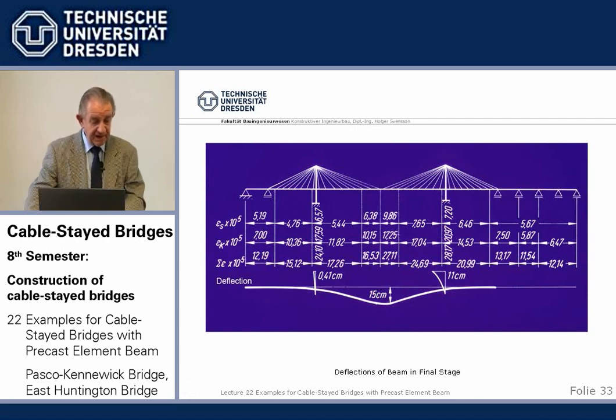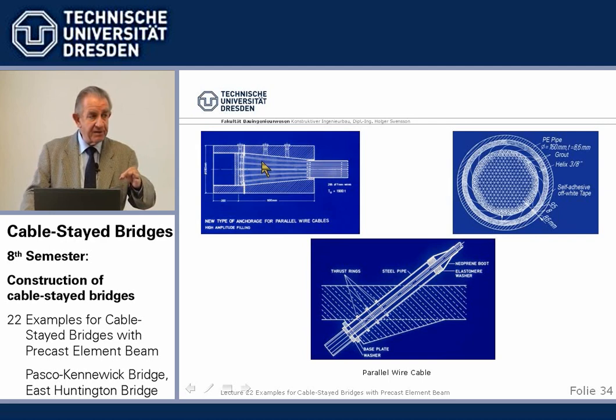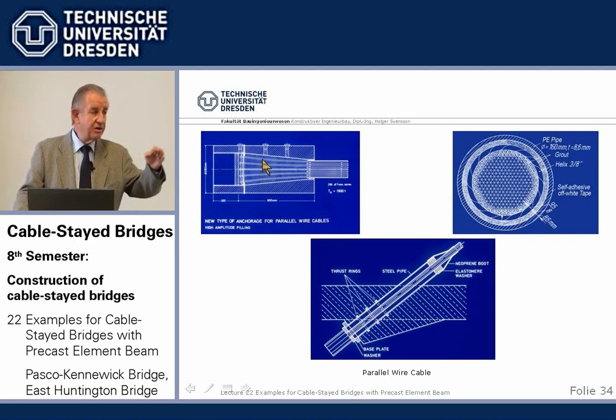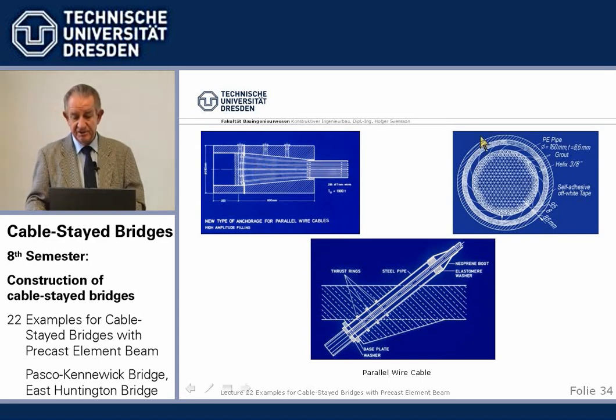Now, stay cables. We used high-M stay cables. I told you all about it. Basically, it's a steel anchor head. The wires protrude and they are fixed with steel balls and epoxy. Cold casting, higher fatigue strength than the hot casting used for the lock coil ropes, where we have the zinc alloy at 420 degrees, which changes the steel, and we have a lower fatigue range.